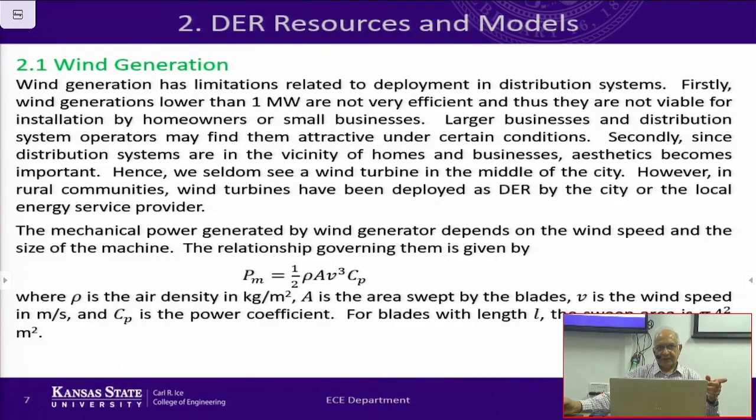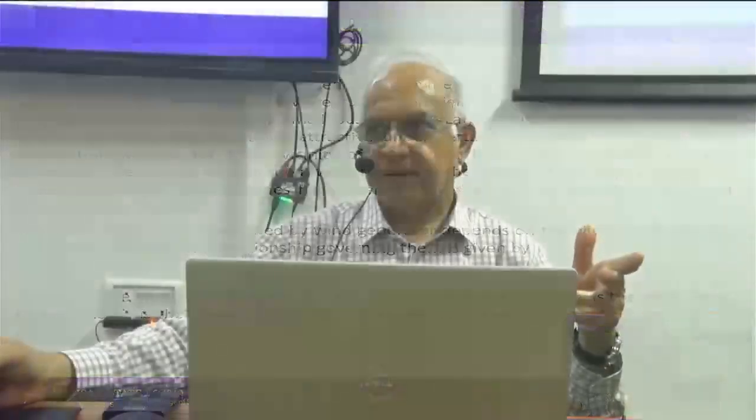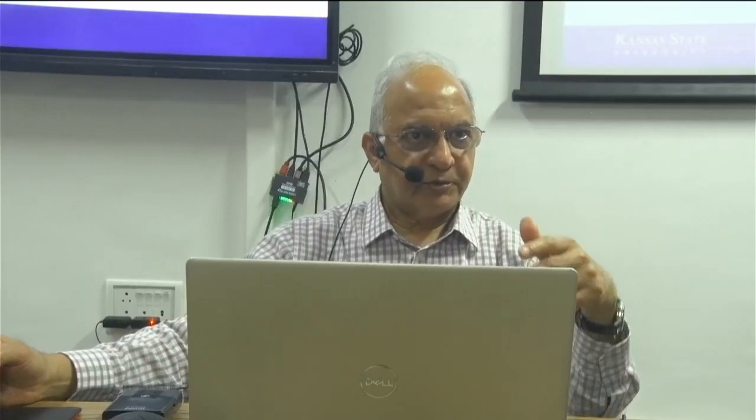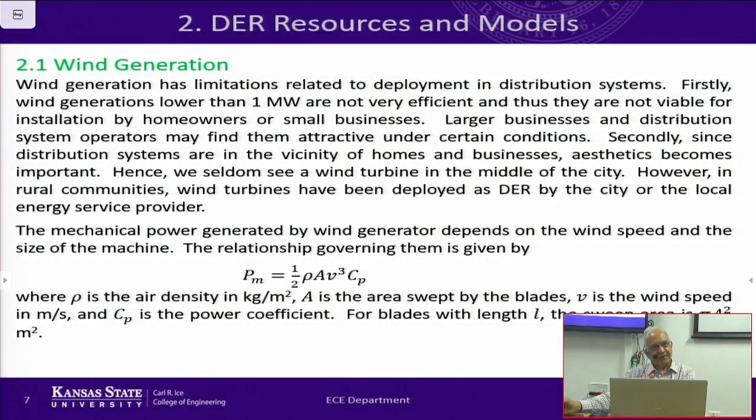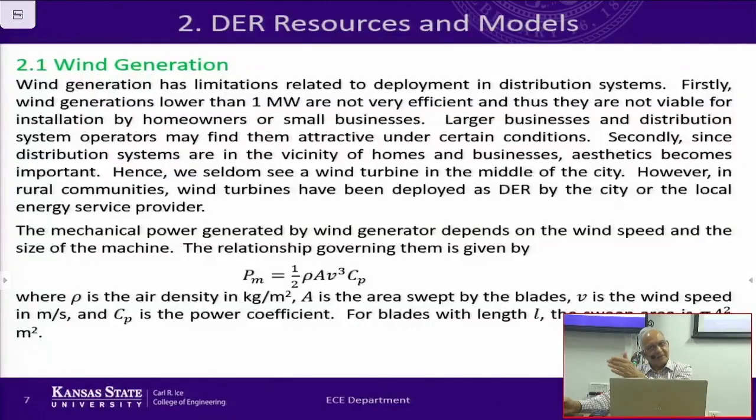And again, wind generators mostly use doubly fed induction generators, and they don't run at constant speed. So whatever voltage is generated, you have to connect it to a power electronic interface, convert it to DC, and then have another converter to go from DC to AC. That AC at the last stage is at the standard 50 cycles, and then you have regulation in terms of control mode.